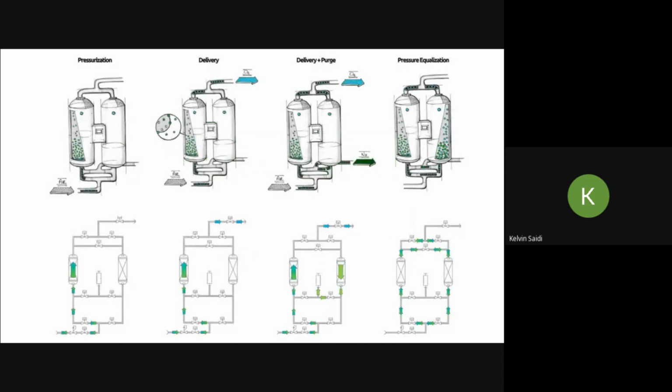Oxygen concentrators operate under the principle of pressure swing adsorption, where ambient air is drawn from the surroundings via the gross particle filter and the intake filter into the compressor. The air is then compressed and fed to one of the sieve beds at a high pressure, and normally this pressure ranges between 20 to 30 psi.